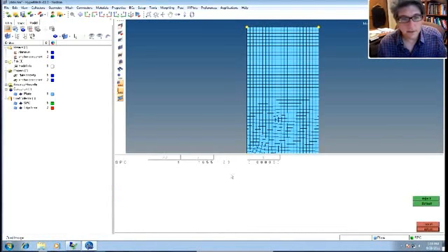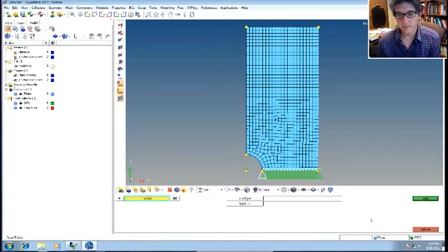Hit edit. And you can see here it is. So the set ID is 1. It's going on node 1655. These are the degrees of freedom. It's fixed, 2 and 3, right? And this is the value associated with it. Okay. Now let's create the ones on this edge.